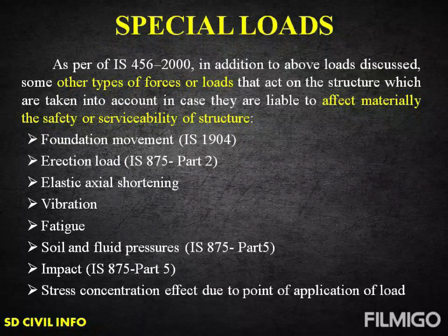Now let us see what are the special loads acting on a structure. In addition to the above loads discussed, as per the code IS 456-2000, there are some other types of forces or loads that act on a structure and they are liable to affect materially the safety or serviceability of the structure. They are foundation movement, erection load, elastic axial shortening, vibration, fatigue, soil and fluid pressures, impact and stress concentration effect due to point of application of load.